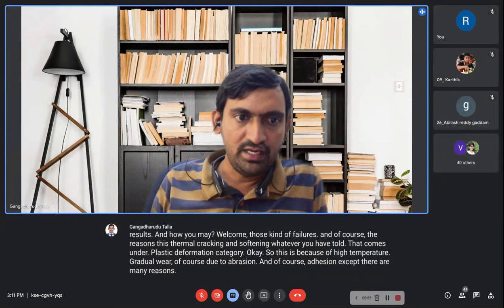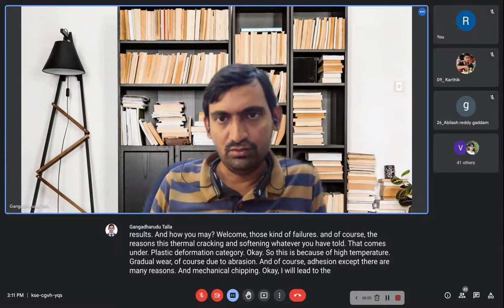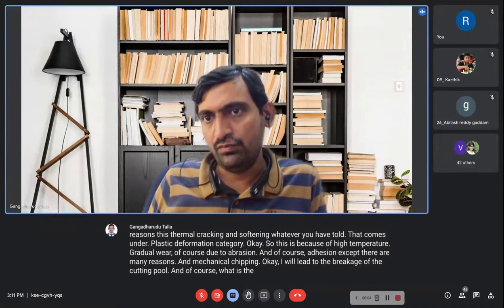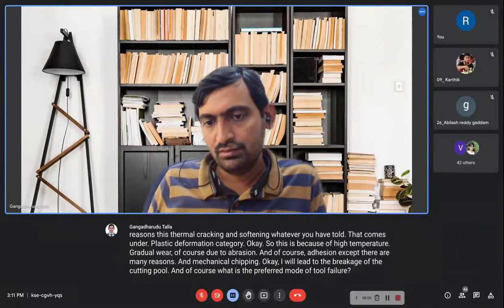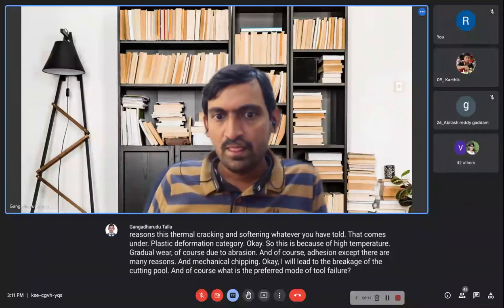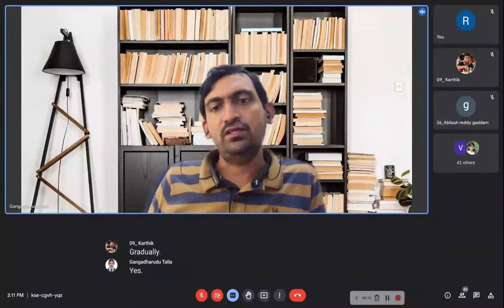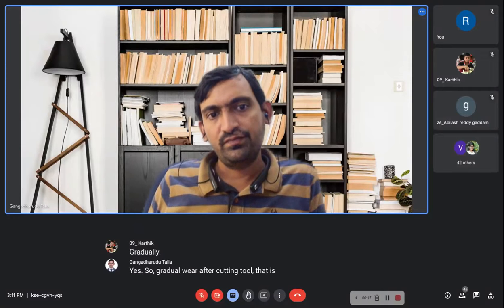And mechanical chipping will lead to the breakage of the cutting tool. And of course, what is the preferred mode of tool failure? Gradual wear, sir. Yes. So gradual wear of the cutting tool, that is what we prefer.